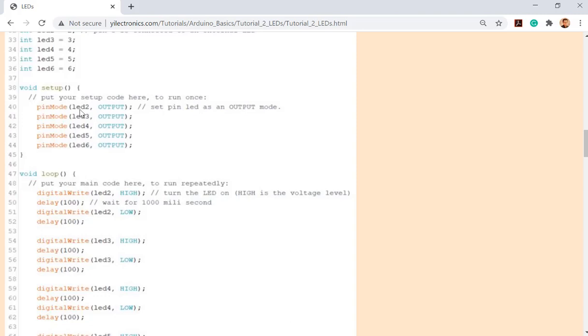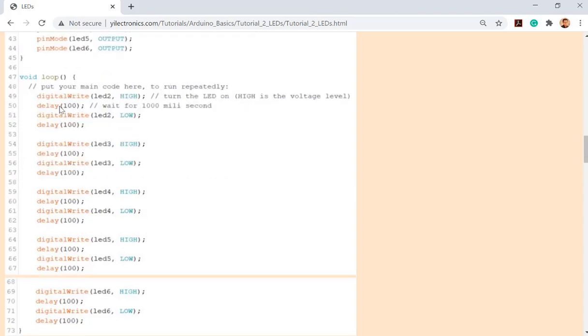So mainly there are 2 functions. If you don't add other sub functions, there will be 2 functions in the script for Arduino. The setup function will only be executed how many times? Once. That's how it was designed. So this will be executed only once, and the loop will run forever.